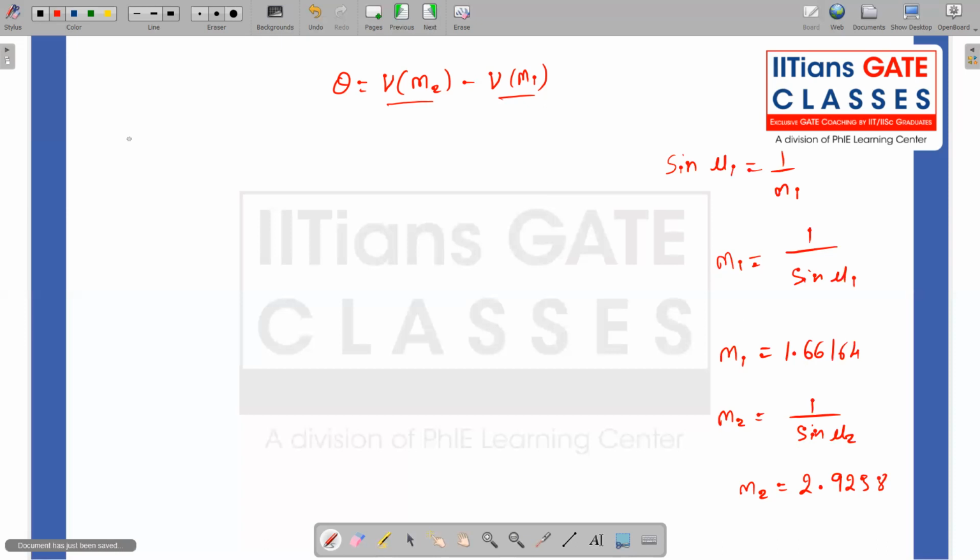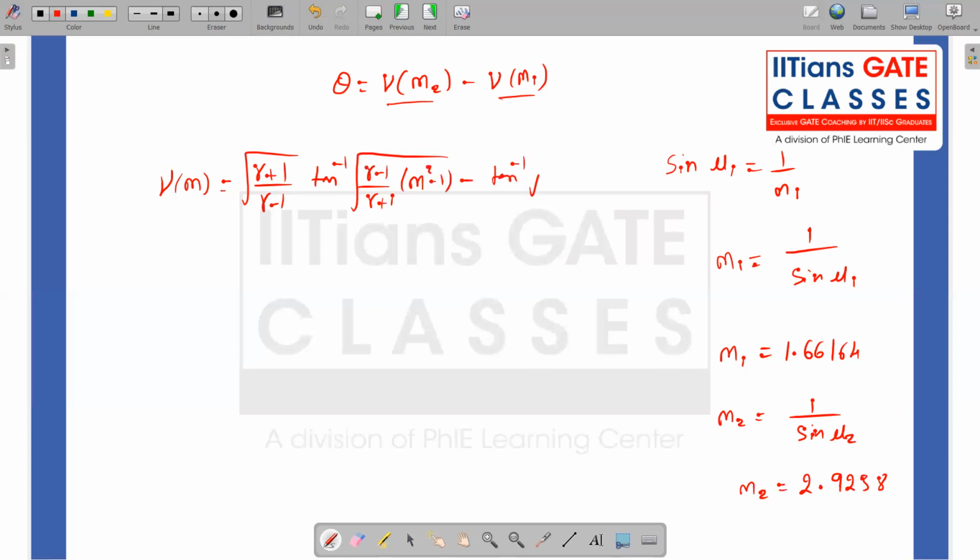Now use the Prandtl-Meyer function. We have nu of M given by root of gamma plus 1 divided by gamma minus 1 times tan inverse of square root of gamma minus 1 divided by gamma plus 1 times M squared minus 1, minus tan inverse of square root of M squared minus 1. So this is the Prandtl-Meyer function we have.